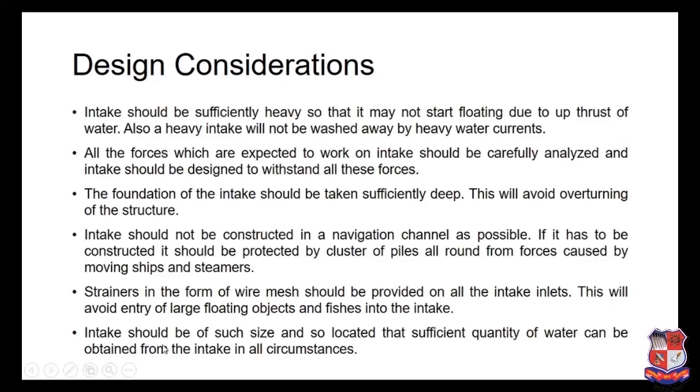And this intake should be of such size and so located that a sufficient quantity of water can be obtained from the intake in all circumstances. So we should be obtaining water during the dry period also. So the location should be provided in such a way that during the driest period of the year, a sufficient quantity of water is always available.